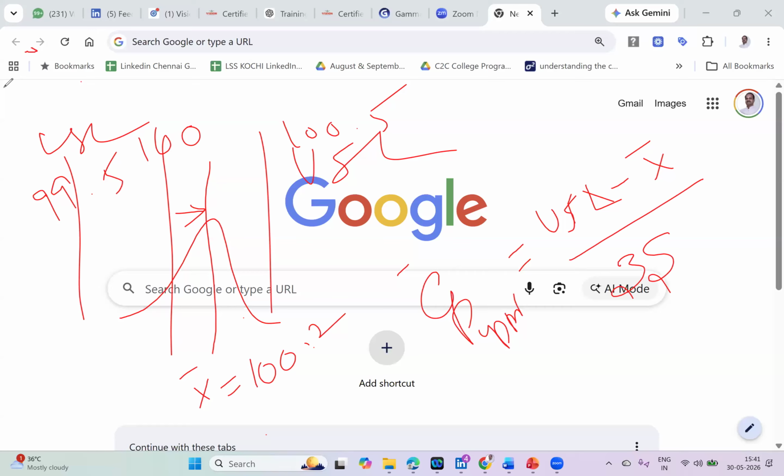Why is the denominator 3 sigma? Because now I have taken only one side, isn't it? Only the upper spec is under risk, not the lower spec. If I want to consider both the specifications, then the spread of the process should be taken as how much? 6 sigma. But now it is only 3 sigma. So this is how you should calculate CPK. CPK will be equal to CP upper the moment you understand the process is shifting rightwards.